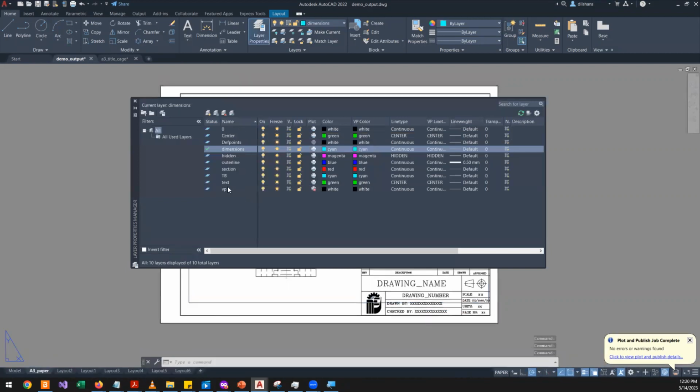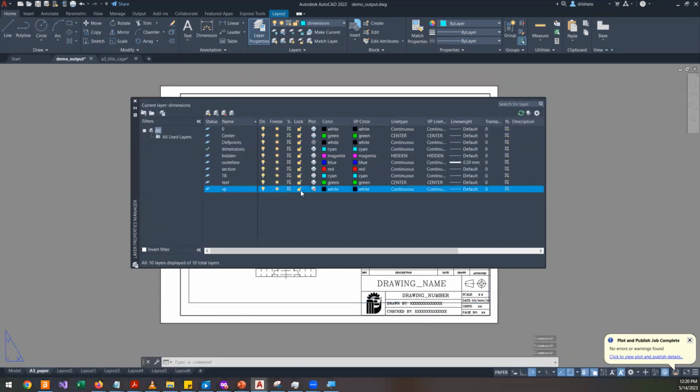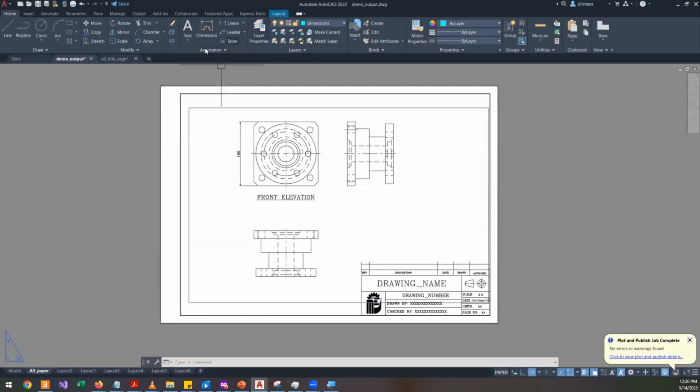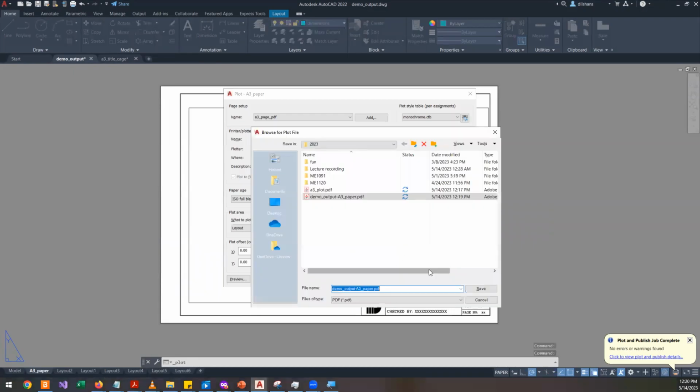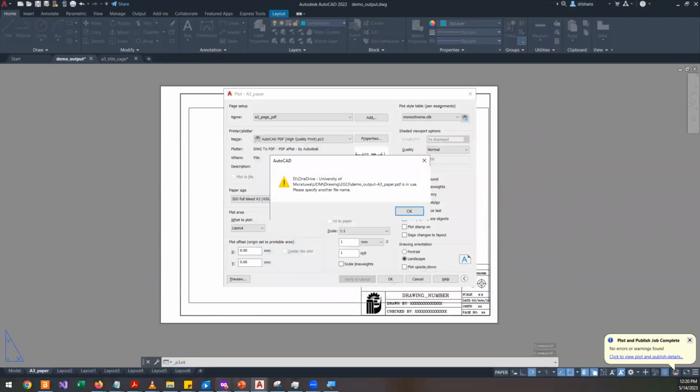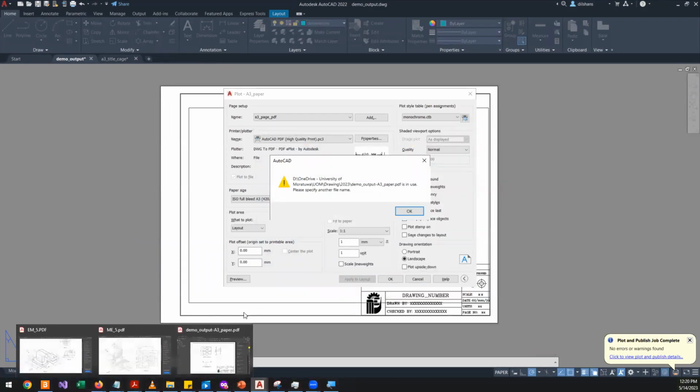So you go to Layer, Viewport, and Disable Plotting. Okay, so simply click on this one if you want to enable plotting. If you see the red symbol, that means everything on that layer will not be plotted. Okay, it will not be printed. Control P. Okay. We have the drawing.